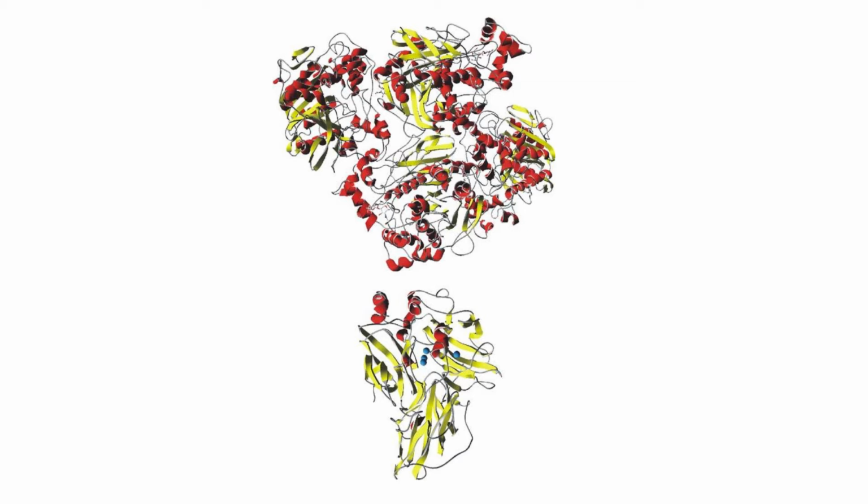Enzymatic pitch control helps to remove pitch-related problems such as reducing defects on the paper web as well as the frequency of cleaning pitch deposits in the paper machine. It also has other advantages such as using eco-friendly and non-toxic technology, improved pulp and paper quality, reduction in bleaching chemical consumption, reduction of effluent load, and space and cost saving in a mill wood yard by using unseasoned logs.